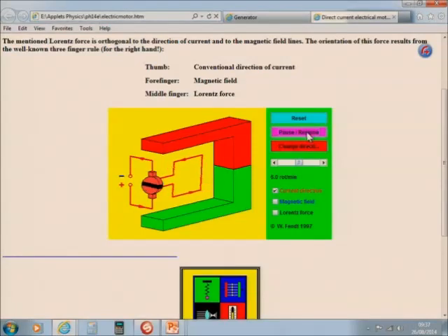Now, if I pause, this arrow is pointing in that direction, this one is pointing in this direction. But as it turns, this part is going to go to the bottom part. So keep your eye on that part and see what's happening when it reaches the bottom part. Right, when it's there, there's a short while when there's no current flowing through the circuit. The reason for that is that when it's on that specific point, it's not touching either of the two split rings. So my circuit is not complete. So for this moment, there's first of all no current in this armature.